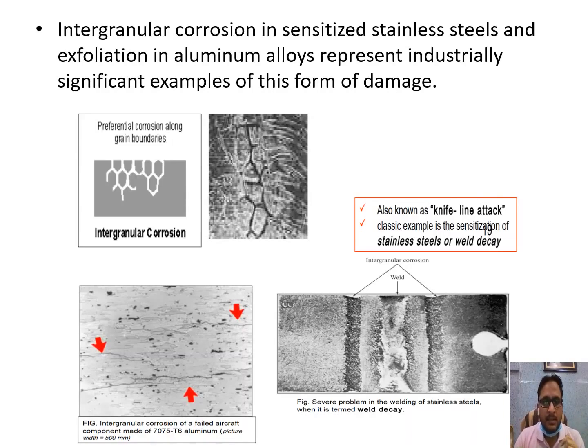the grains are clearly visible. So grains and these types of lines, these are grain boundaries. Through these, corrosion starts taking place, and this is only because of the excessive deposition of more corrosive metal near grain boundaries as compared to grain centers. Intergranular corrosion occurs in sensitized steel, but it can be stopped or prevented by heating the metal uniformly.